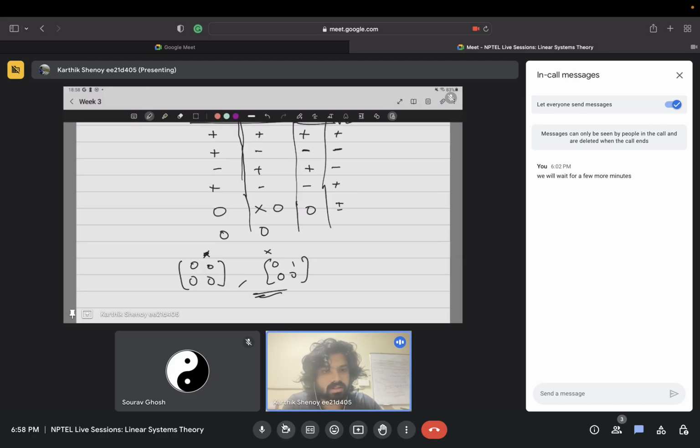So what does this mean? There are two poles at the origin, correct? If you look at this matrix and convert it to state space, you know that the eigenvalues are 0 and you have repeated two poles. This in fact is an unstable system, right? So you will see what the significance of the algebraic and geometric multiplicities are. Okay.